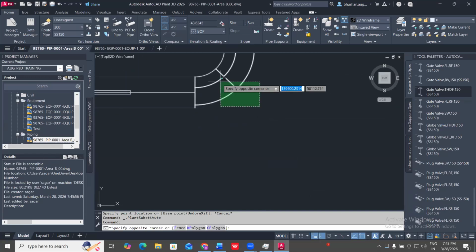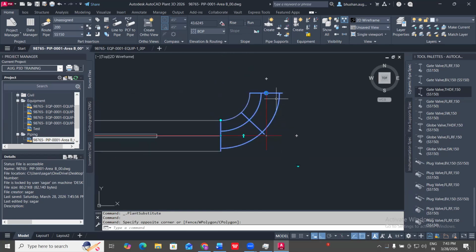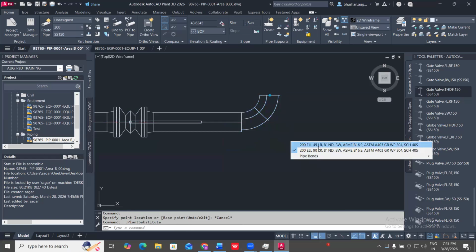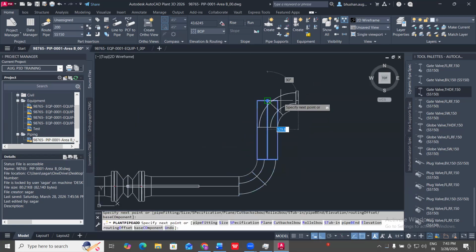And for the elbow, when you want to add a 45-degree elbow, you need to have one end open. Okay. If you want to use the substitution part option, because if it is not open, then it would only show you the option of 90 degree, because it has already been given the constraint, and constraint means it is already connected to two parts.